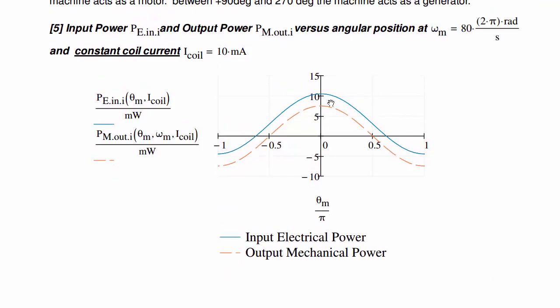We note the magnitude here of the power. We're on the order of 10 milliwatts input. Now this is instantaneous, so the average input power, if we were just driving during this minus 1/2 to plus 1/2 pi, basically 180 degrees, and did nothing for the other 180 degrees, would be the average of this sine wave over that period, divided by 2, because we only do it for half of the full cycle.